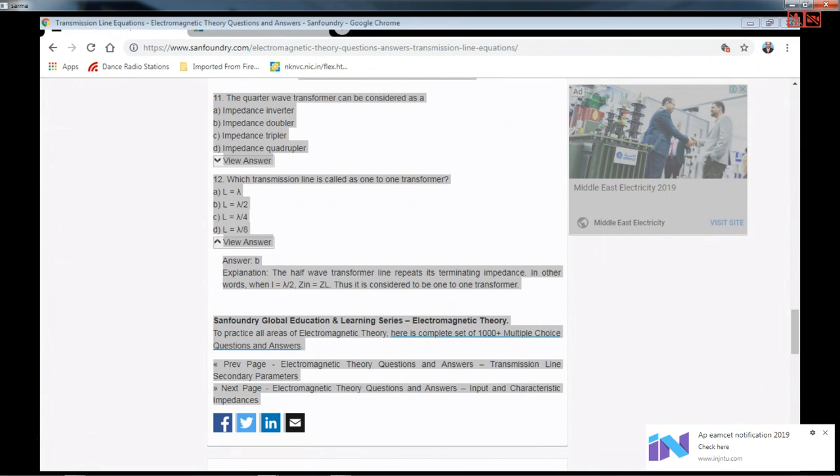Okay, so unless otherwise specified, let us not get confused whether it is voltage reflection coefficient or current reflection coefficient. We talk of only voltage reflection coefficients, which will have +1 for the open circuited case and -1 for the short circuited case. Standing wave ratio will have a range of values possible as 1 to infinity for any case. 1 is the most favorable situation. Infinity is the worst possible condition as far as the transmission of the power is concerned.